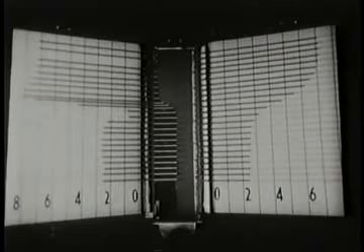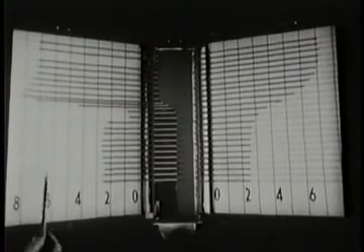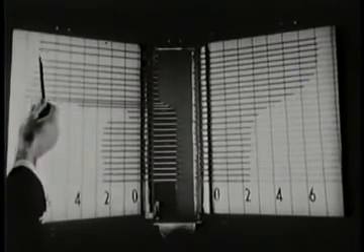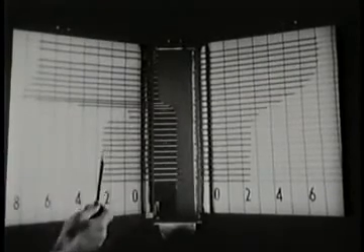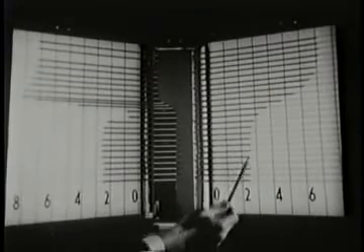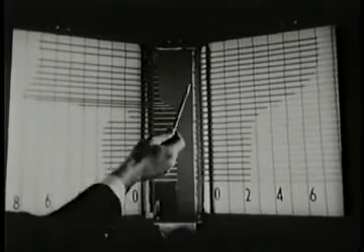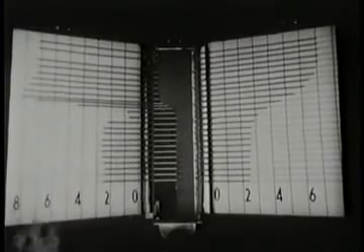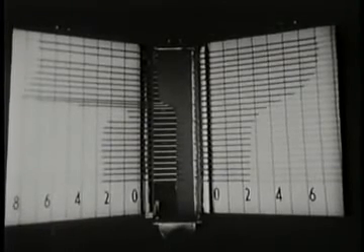Our flexible wall rig now is in the form of half of a rapid symmetrical contraction. Upstream, the pressures are equal on both walls. Downstream, they are also equal, but lower. Because of the area decrease, the average velocity increases, and, according to the streamline equation of motion, the average pressure falls.